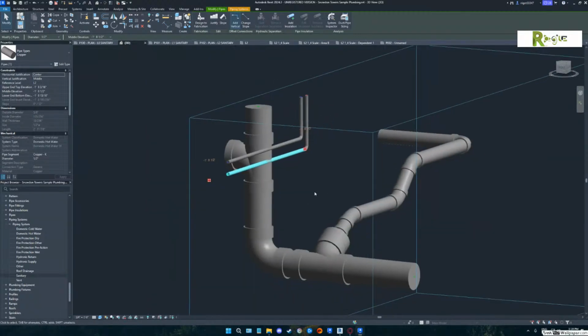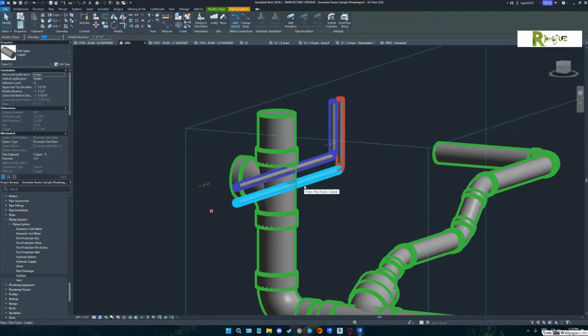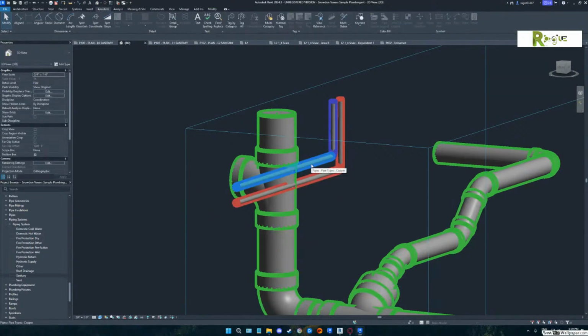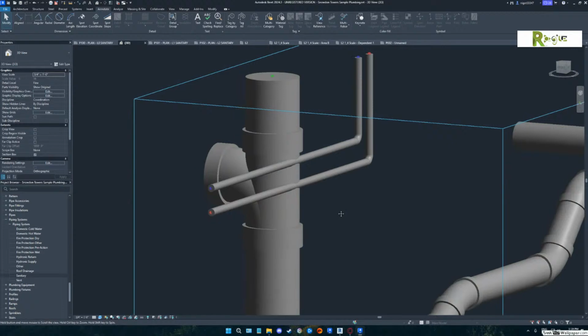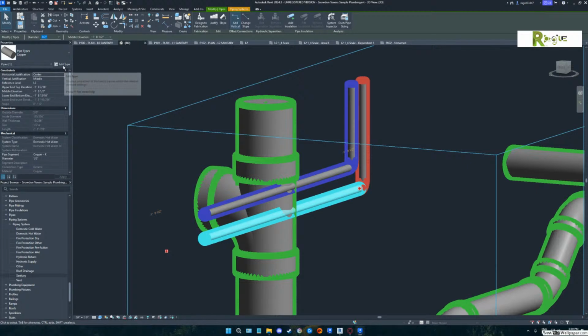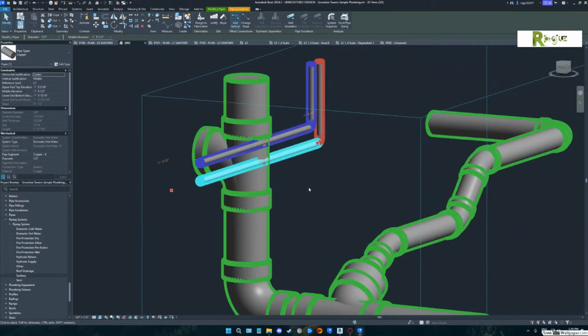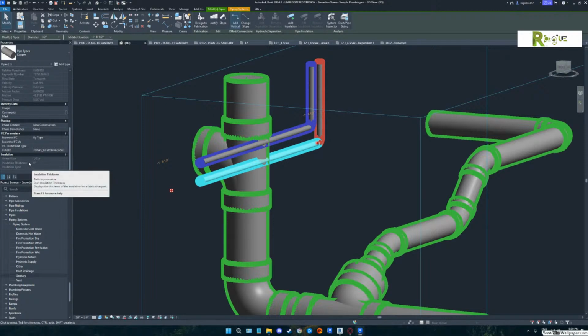Hot water will typically have an insulation on it. So will the cold, but the hot's going to probably have like 2-inch insulation. Right? It doesn't look like it has any insulation on it. Scroll down in the properties box when you have it selected. Insulation 1/2 inch. Insulation thickness 0. So yeah, no, it does not have insulation applied to it.